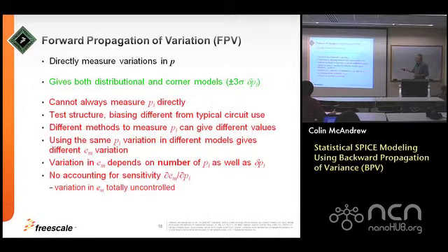So if I get the parameter from a very different measurement condition than the one I'm going to use in practice, that's not a good thing. For example, modelling people, when we measure MOSFETs, we like to measure at very low VD because it gets rid of the effect of velocity saturation, DIBL and channel length modulation. So we do that to get the parameter values. But in an analog amplifier, you're going to be operating that device at a large VD in saturation every time. So it's a very different biasing configuration. If the model's not perfect, I might have fitted the parameter in one region, but then use the model in another region, and so the prediction of the spread for that parameter is not necessarily accurate.